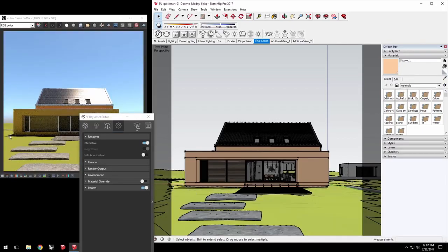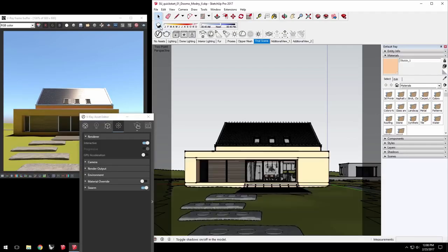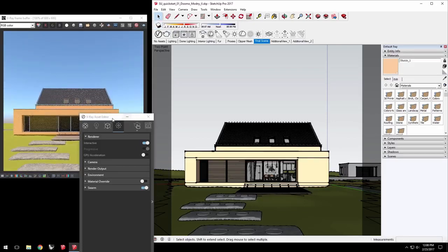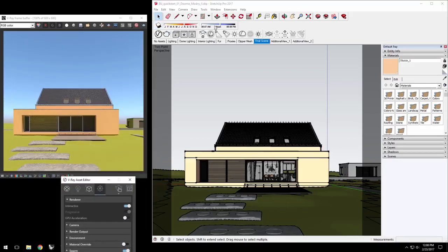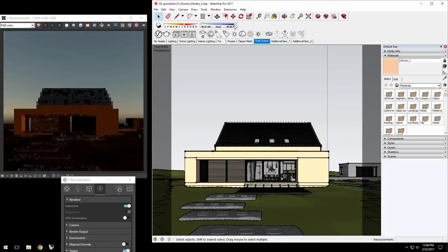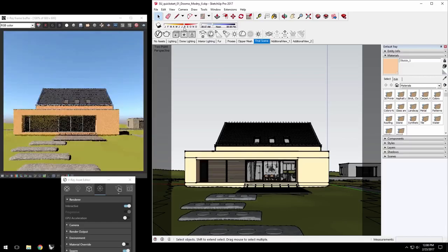To keep things speedy, disable shadows in SketchUp itself. Go ahead and change the date as well to see how the sunlight changes. Change the time of day, like to the evening, and you'll see that the sunlight not only changes direction, but also its color as well, changing the sky background for a dusk setting. Experiment for yourself, but when you're ready, go ahead and set this to a late morning time and sometime in August. Bring up the Asset Editor.